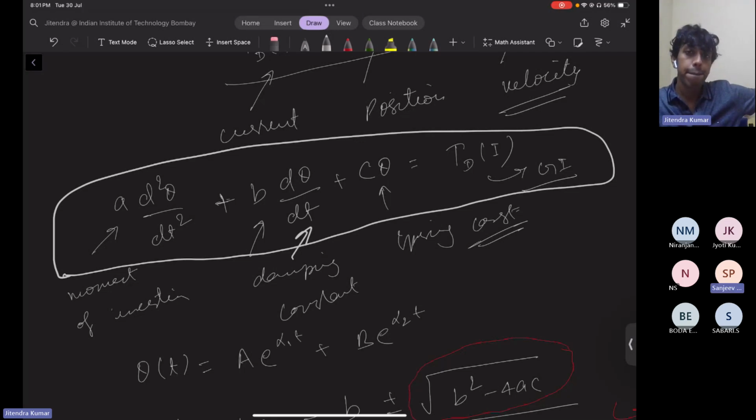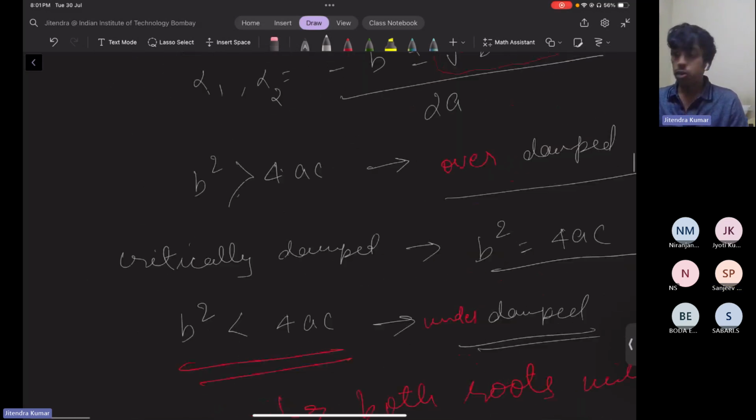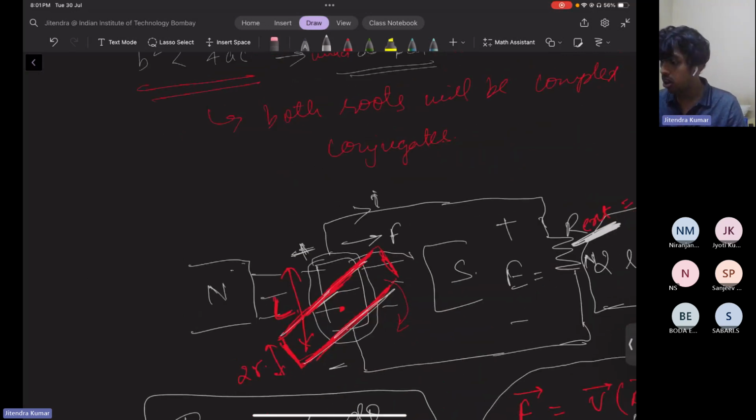Sir, will the value of theta be given in this way? Yes, if they ask for damping torque, then they will mention it in terms of theta, like 5 sine theta or something, or 5 into some theta. Then you will have to differentiate that expression. Okay. So I hope you all are able to understand the concepts behind this dynamic equation and the PMMC instrument especially, and I hope you are able to solve the question.